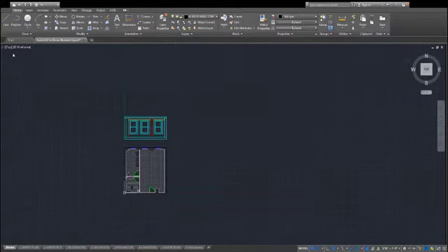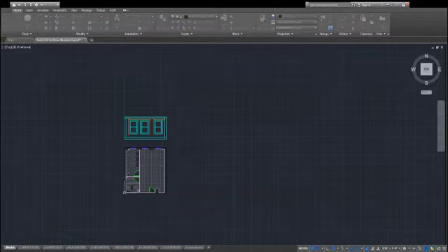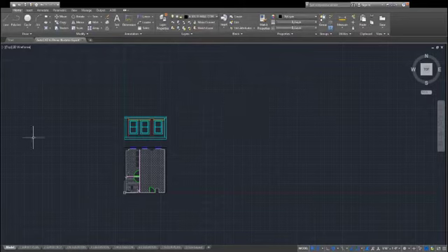So here it is. I'm going to save this as a drawing file. I'm going to name this AutoCAD to Rhino Illustrator Export DWG, and then make sure that it's on the 2000 version of AutoCAD, not 2018, 10, 13, or 7, but 2000. I'm going to save this. Now this is ready to be opened or imported into Rhino.